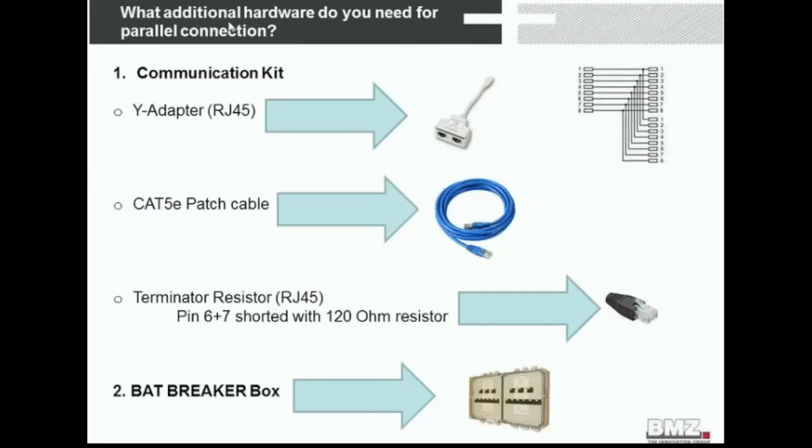You need some additional hardware for that, but the good information is this hardware does not cost much. You need a Y adapter for the internal communication. You need a patch cable, which can be Cat5e, for example, and you need terminator resistors. Every terminator resistor is around, I don't know, €2, not that much.